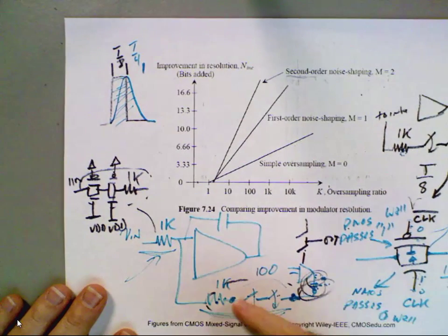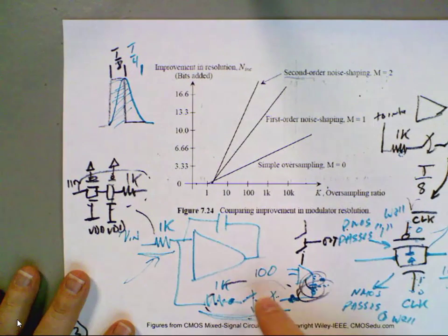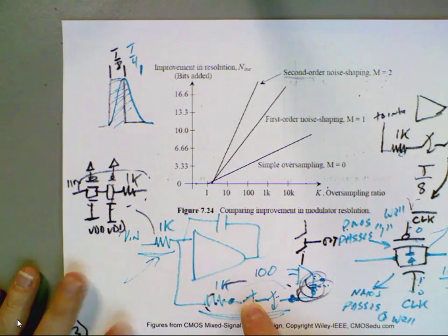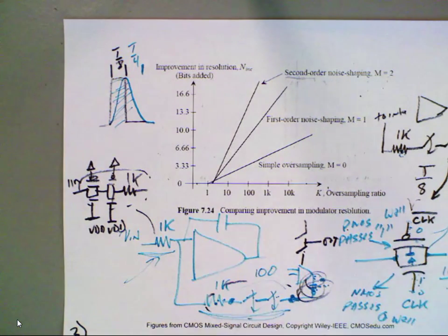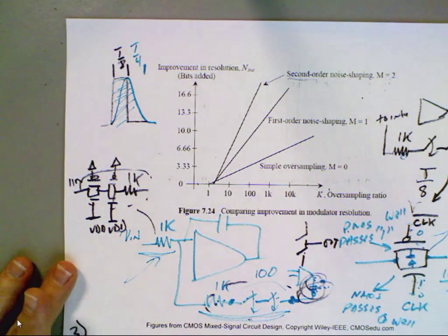Look at the current through the resistor, because it may be that your gates are turning on, and you're looking at, oh, the gates turn on nice and fast, but you don't know how fast the actual transistors turn on, and you start getting current flowing through them.